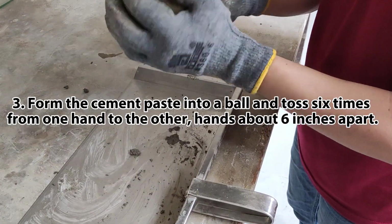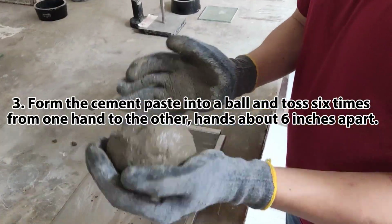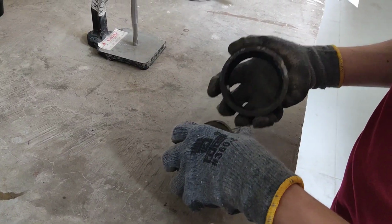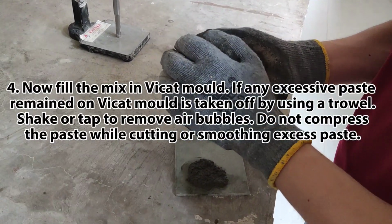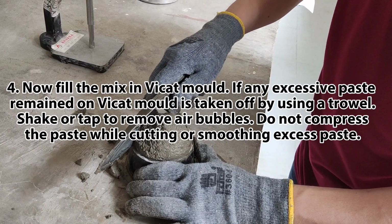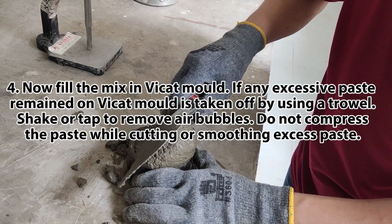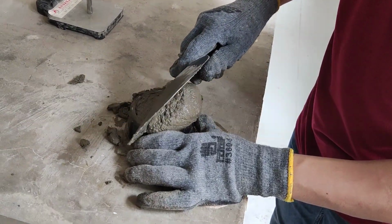Third, form the cement paste into a ball and toss 6 times from one hand to the other, hands about 6 inches apart. Now, fill the mix in the Vicat mold. If any excessive paste remains on the Vicat mold, take it off using a trowel. Shake or tap to remove air bubbles. Do not compress the paste while cutting or smoothing excess paste.